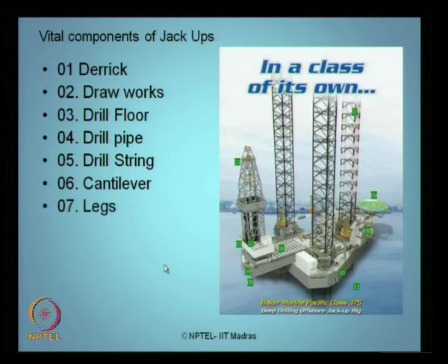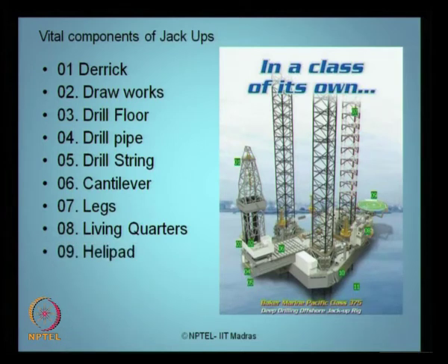The 7th component what you see here are the steel lattice towers, which are otherwise called the legs of the jack-up rigs. 8 of course is the living quarters. You can see the complicated living units here where people who work on the rigs live. 9 of course is the helipad facility for helicopter landing, and 10 is what you see here, the hull of the jack-up rig.